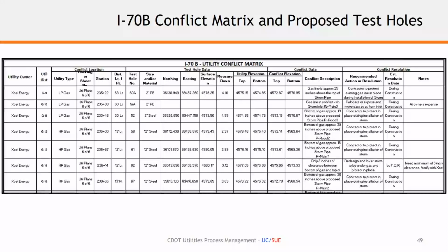So the loading requirements, potentially the compaction requirements over the top of that need to be identified as safety critical work, where the contractor can store vehicles adjacent to that line, or where it crosses that gas line, and how the contractor protects that line during construction. Having that measured down and that data here led to identification of other issues further along in the project.